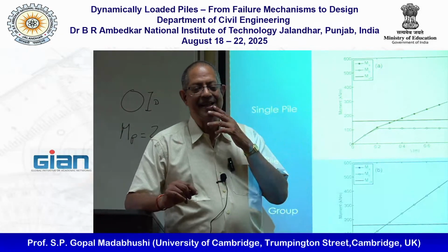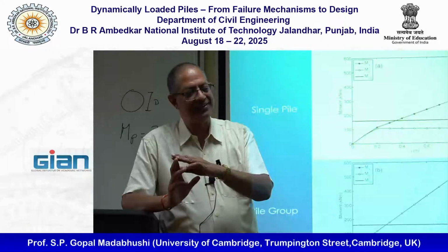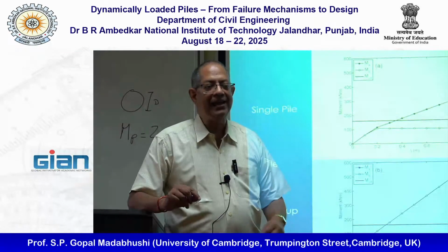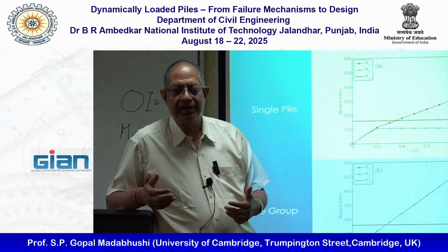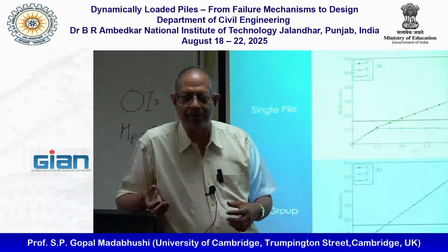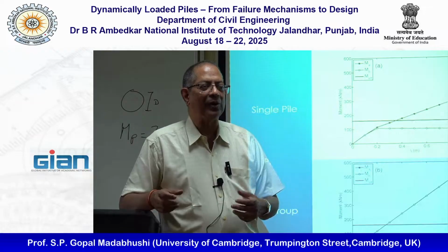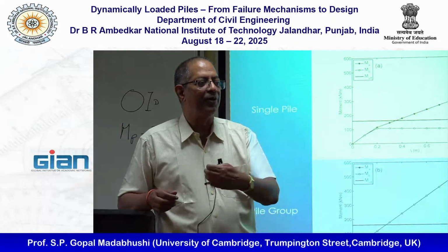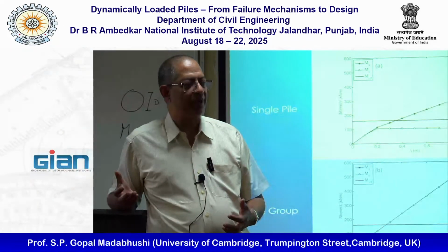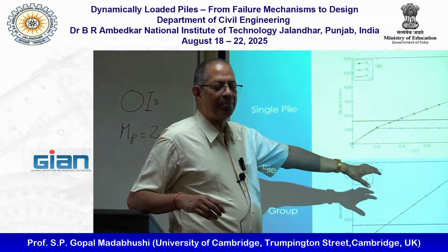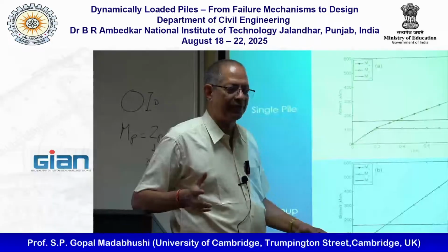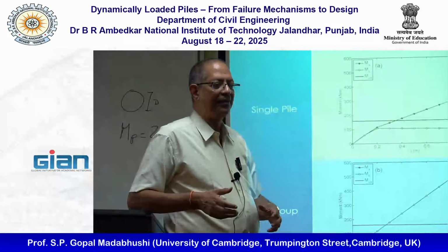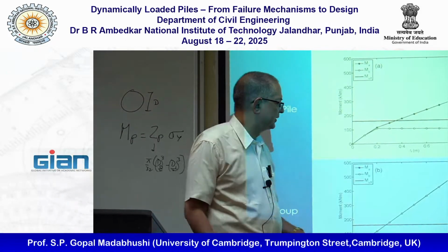The problem with piles is, once you reach the plastic hinge, that means I've already undergone 0.3 meters for this particular case, right? Then the P-delta effects start to dominate, because I still have to carry the axial load. So the worry is that although I have this plastic moment capacity, the more deflection I give, the worse it gets, the more the P-delta moment will become. So that hasn't percolated to piles, and nobody has done enough research to say, after the plastic hinge has formed, how much load, how long before I will completely collapse the pile. So there are reasons for it.